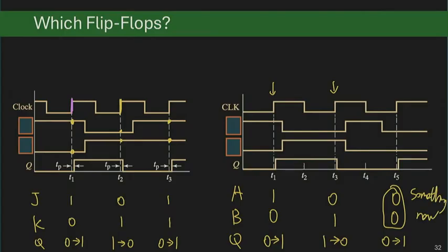You can definitely define 0 to be toggle, 1 to be hold, and then try to manipulate the NOR gate, NAND gate to really build it. But it's none of what we have seen from those 4 examples. This is not an SR, this is not a JK.